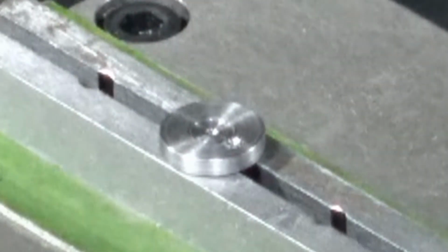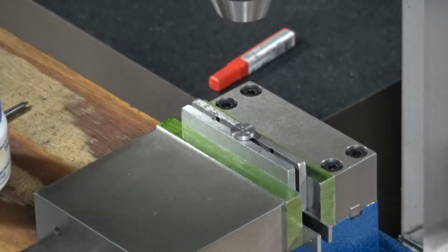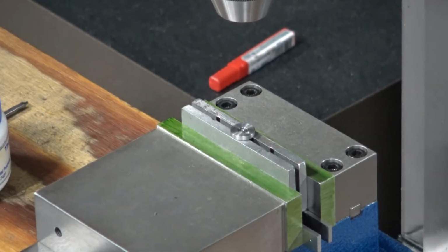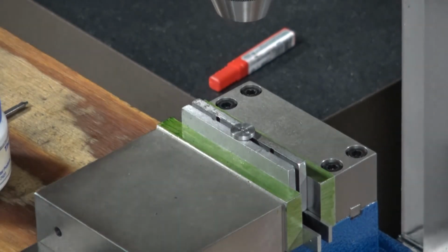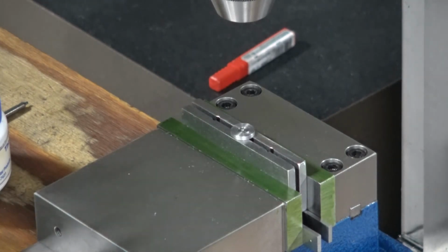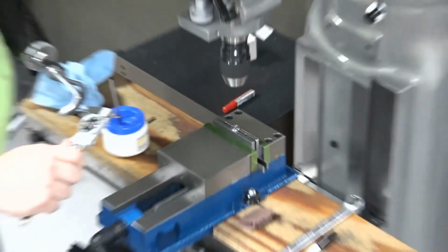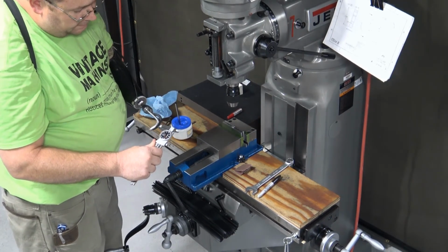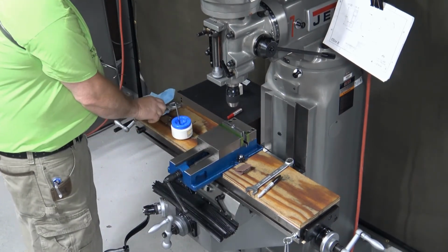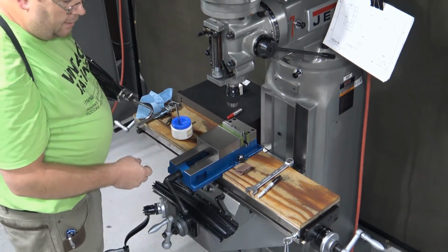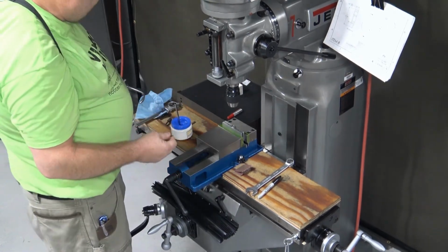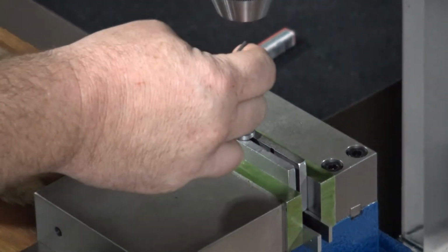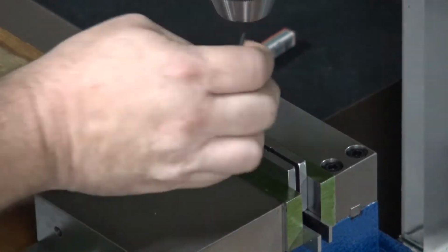I'm going to take my drill bit. I want to double check that measurement because this drill needs to measure somewhere around 116 thousandths. And it's reading 117, which tells me that within the thousandths or so error that my dialing or my calipers have, it is the number 32 drill.